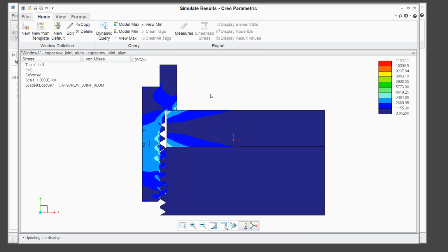Other stuff would include vibration, where we can actually get magnitudes, like on a random vibration or a sine sweep simulation. We haven't talked about thermal here. The software does thermal conductivity, and it can also do transient problems where the heat load is time variant. And there's a few other things. One of the things that's really good is the bolt idealization. It's a method of holding bodies in an assembly together, essentially using spring elements. And you can now do those with preload and all kinds of neat stuff. So if you have bolts in your assembly, it's pretty easy to put them in.